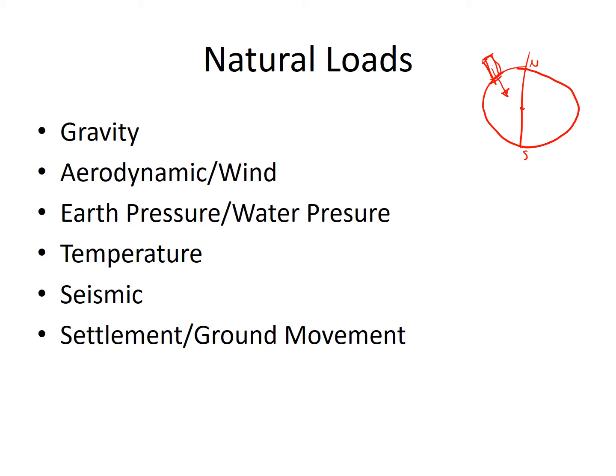And we saw in the previous slide that the load path has to be competent to get it to a point at which that can be met by a reaction. So the total loads in this downward direction have to be met by a reaction force which is equal and opposite, in order for that structure not to move under the load, or to accelerate under the load.